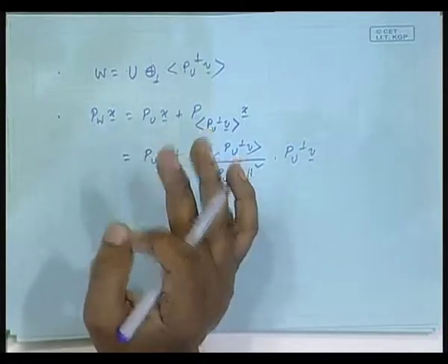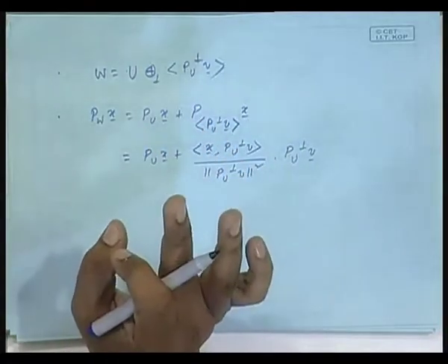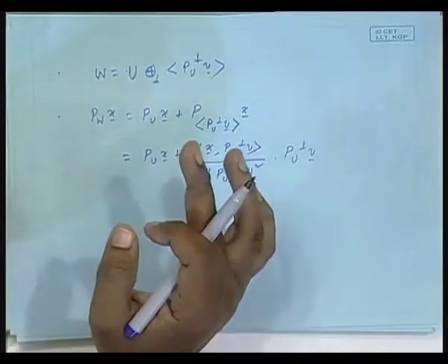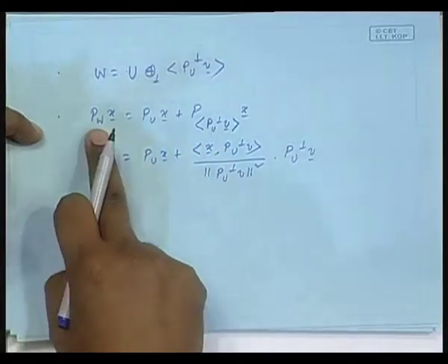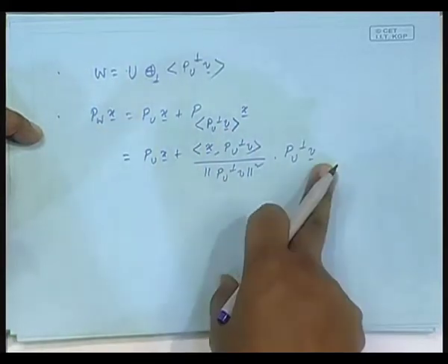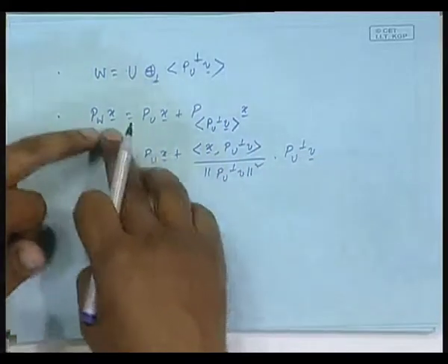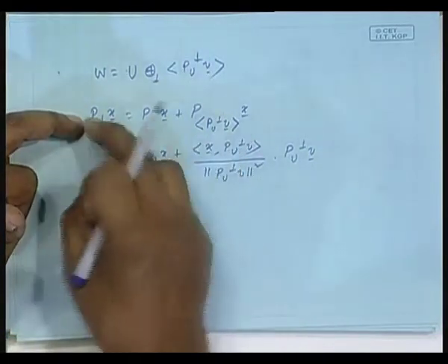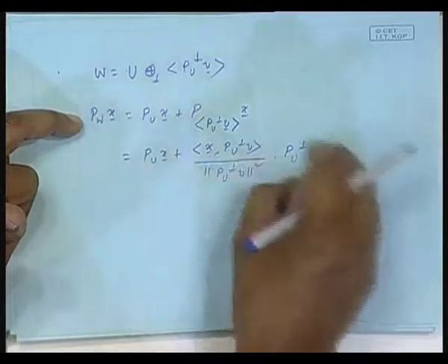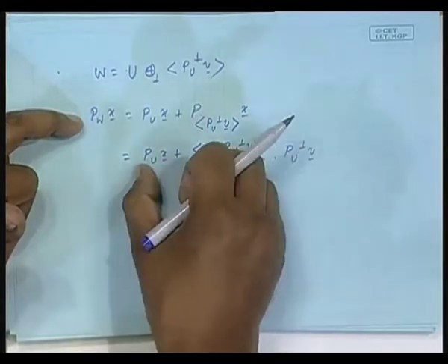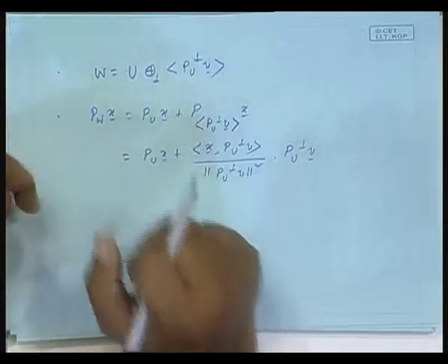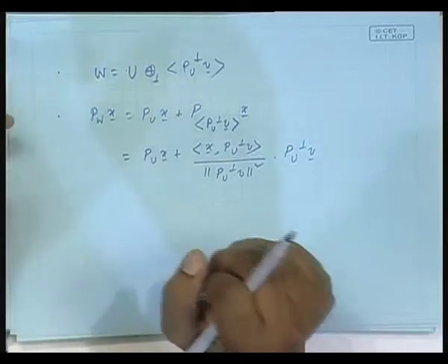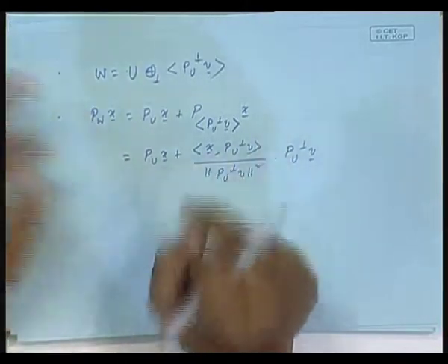So, the number of elements is the dimension. If instead of dimension you call it order, say, using filtering, your DSP language, order was R, order became R plus 1. Old projection, new projection in terms of old projection plus an extra term. This is called order updating the previous projection. This was the previous projection. New projection is what? Your order updating. This is the update term. Adding an update term to the previous projection, you get the new projection. Okay. Never forget this. I will use this many times.